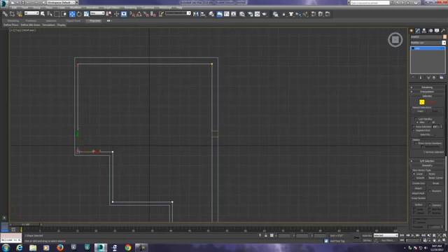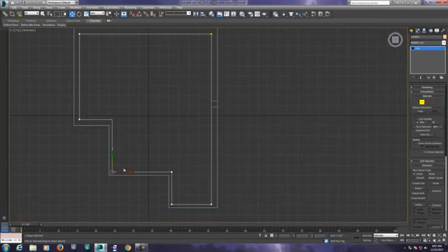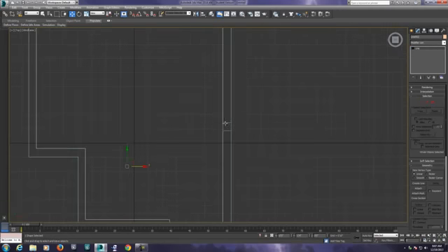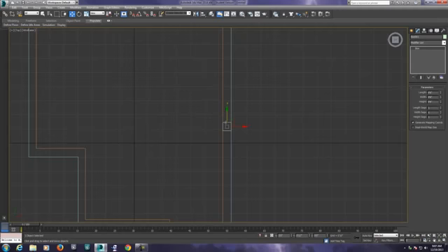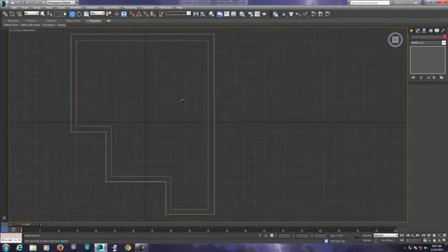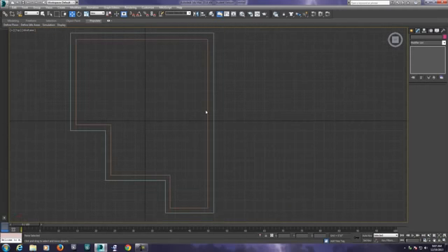If you want to be incredibly accurate, you can move that reference box around and give yourself an exact measurement. But again, the exterior and interior wall dimensions are not critical. The only thing you're going to notice is, when you look out the window, the depth between the windows. So this would represent my room.